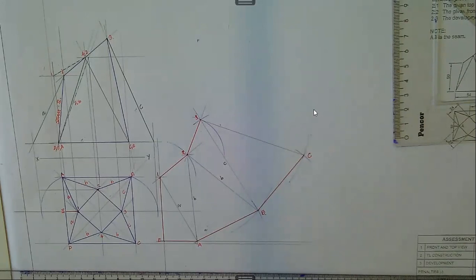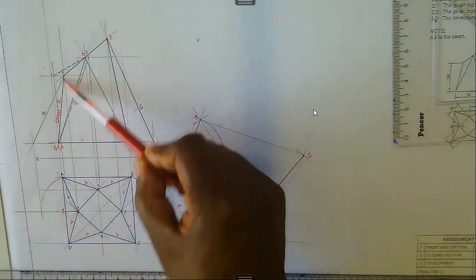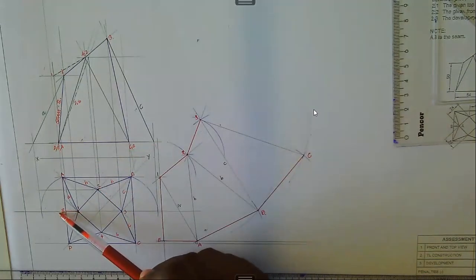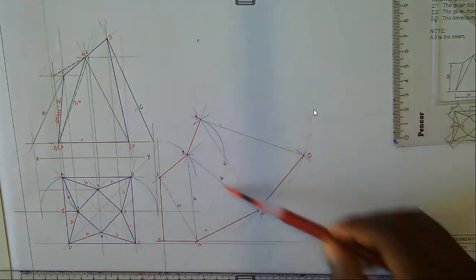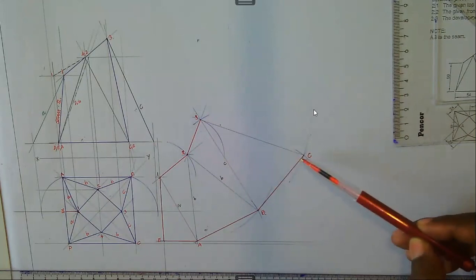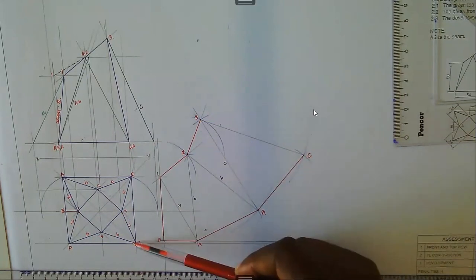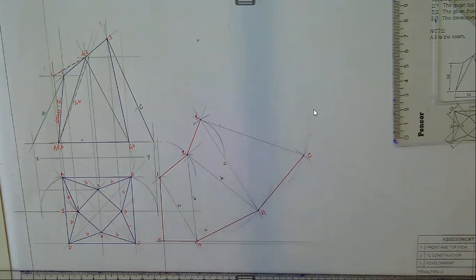So from the start, that's the seam line which is given by virtue of its position. Then we started creating triangles. And these are the true sizes of those triangles in terms of those panels. The triangles are patched together, or they are connected together, in order to develop the template that we are working on. I now have got point C and point 3. The next one that I want is point number 4.